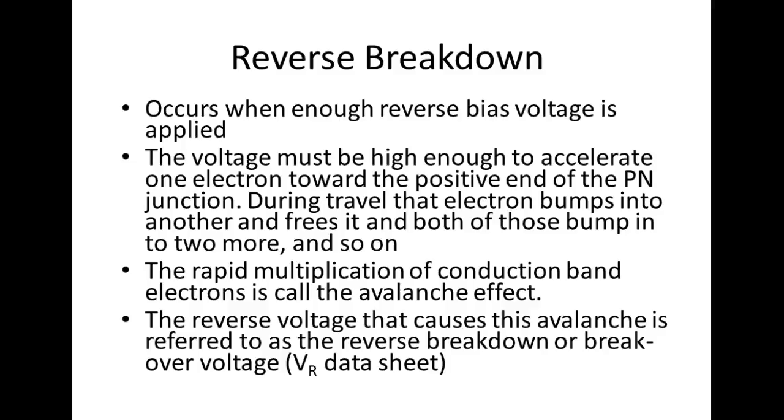If you exceed the breakover voltage for the solid state device, there is a high probability that something's going to happen. Either it's going to short or it's going to open. Normally resistors, I've never seen a resistor short. I've seen a shorted resistor, but somebody did something wrong. They were soldering and dropped a solder blob across the leads. Or when they clipped the leads, they clipped them too long, and when they pressed it up against something, the leads touched. Resistors, when you heat them up and they start going bad, their resistance goes up.